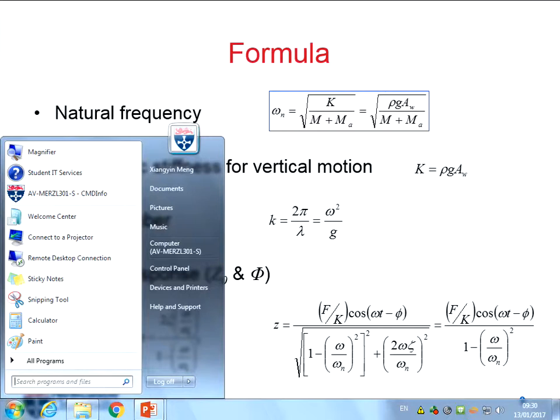Another important thing before we calculate any forces from waves is the speed potential, or velocity potential. And for the expression, I think we have a very good one from the table. This expression is based on the assumption that the water depth is very high, the value is great. So we can have a simplified expression here. And in our calculations, because it's for open seas operation, we always assume, at least in my part, that it's for deep sea. So we can just use the expression in deep water. Okay.